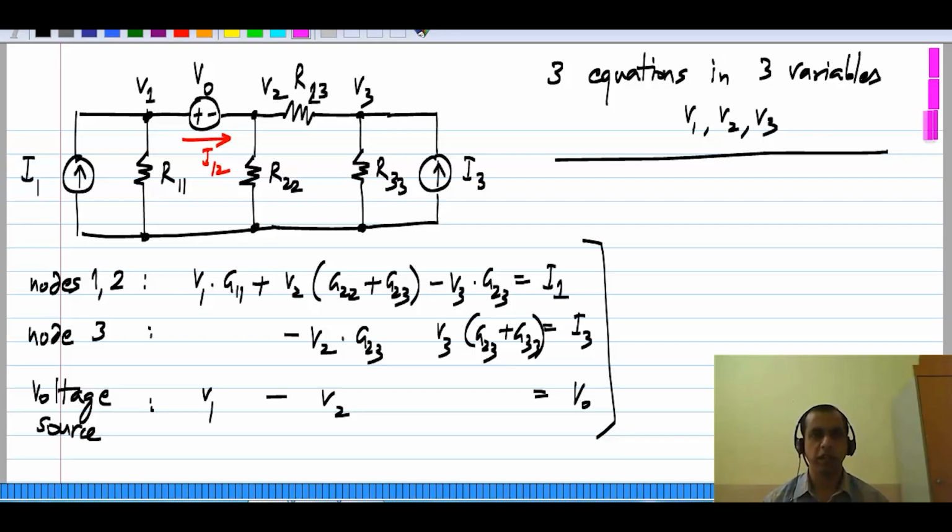What we would still like is a straightforward way of writing down all these equations without going through this intermediate extra variable. If you remember, that's what we did for nodal analysis also. We started out with Kirchhoff's law and then identified each of the currents with the voltages across them and the resistances in those branches. But finally, when we wrote down the structure of the equations, we could simply look at the circuit and write out the conductance matrix. So that's what we want here also, and that's possible as well.